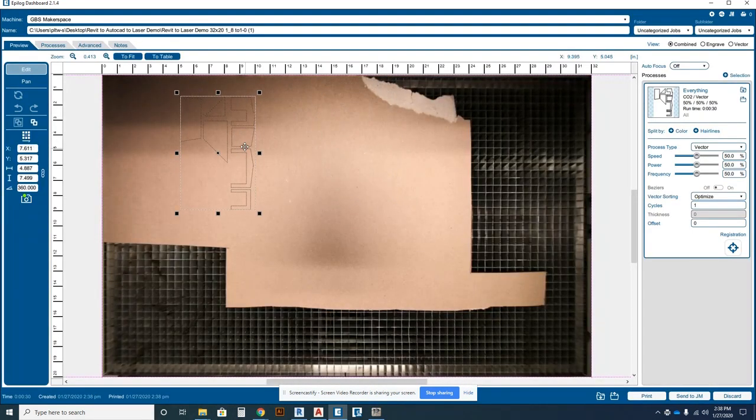Now here I have my actual item. And if I hold down Control and use the rotate command, it'll snap it orthographically or at default angles. So I'm holding down Control, and I'm going to pick it in an area that I think fits it well. And then I'm going to go and place this up in the corner so I waste the least amount of material. The worst thing I can do is just place it right in the middle. I'm going to waste a lot of material that way.